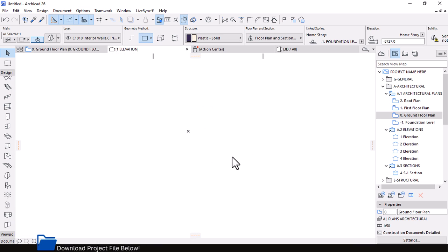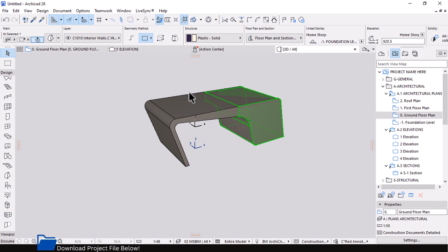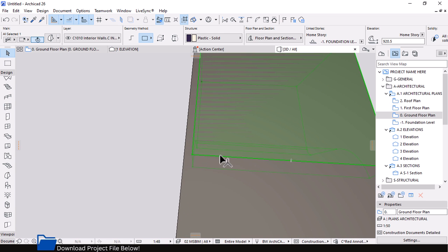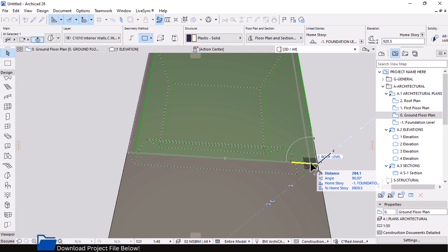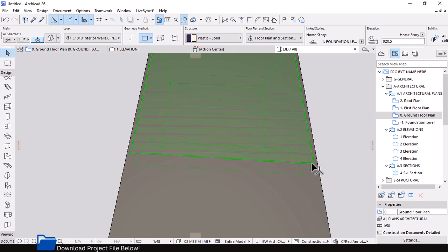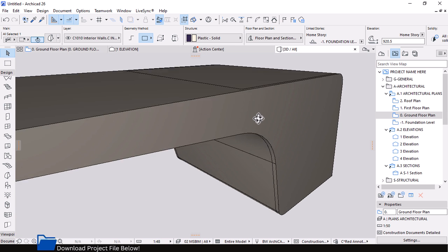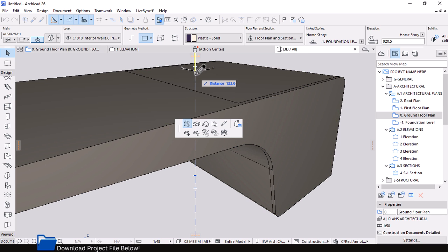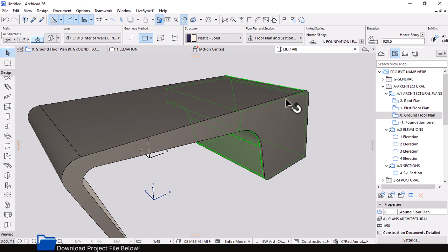Let's go back to the elevation and raise this to the 0 level like that, and then go back. As you can see, it has to be positioned well. You can also do it on a 2D plane or here on the 3D. What I need to do is move it, Control D, to move it centrally, by 150, something like that. And then I think I need to drop it down by selecting the surface and extruding down by 200. Yes, something like that.